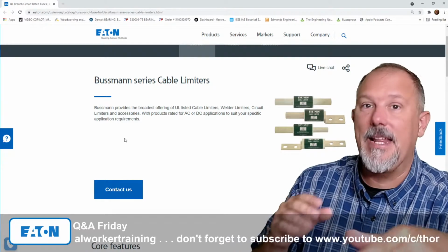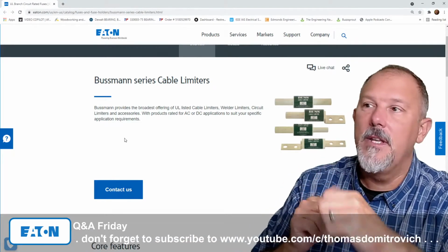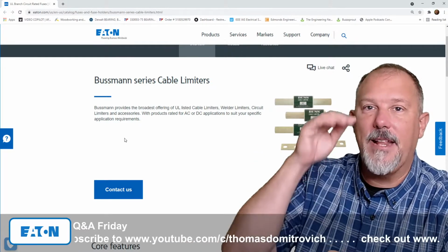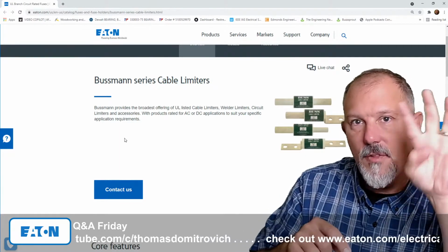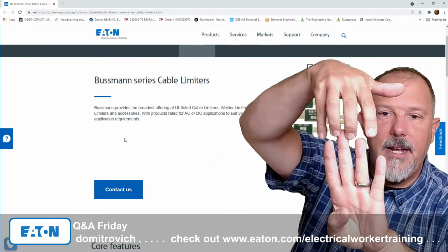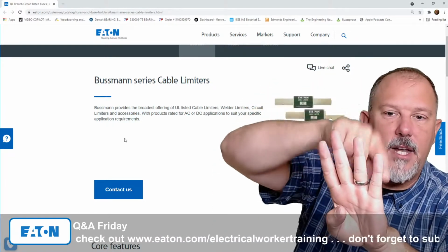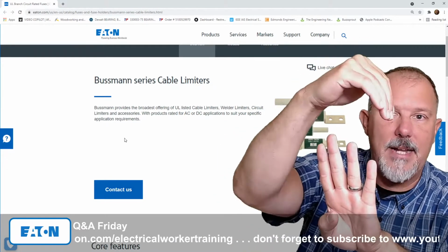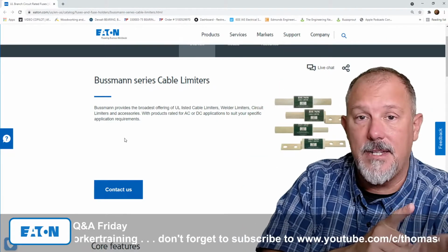And what would typically happen, it'll probably open on both ends, okay? Because if you have a fault in the center, at the source it will open. Say there's 4 conductors, and I'm protecting on both ends. This conductor fails. I open this side, but then these 4 will serve the fault back down and through, and then I'll open it on the other side, and I isolate one of the conductors.